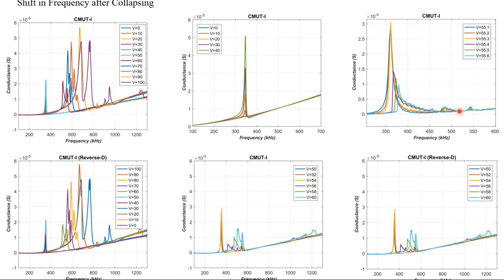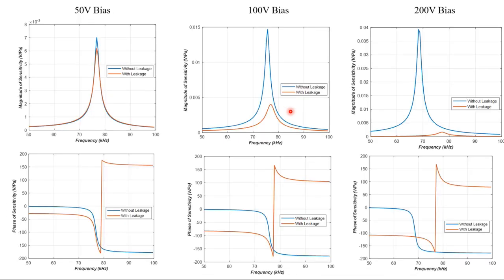Some comments on breaking loss: in particular, if I talk of the uncollapsed states of CMUTs, there is no spring softening if you see these baselines. This is what I measured, based on the data, and this is what we have simulated. So the spring softening is gone, and the receive performance is compromised.